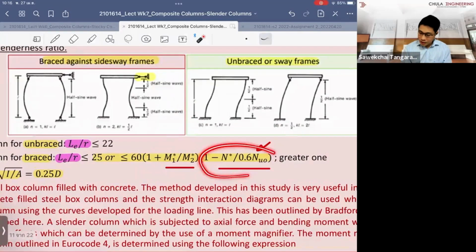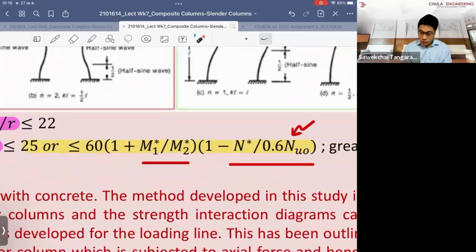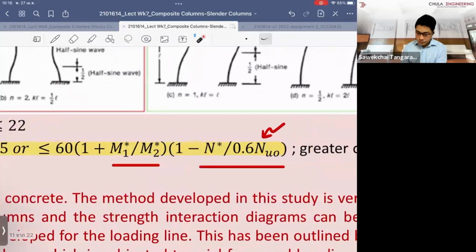The last term is the ratio between the F' and you have the star as well. Don't forget you need to come with the load factor as well, right? And we use it in all the designs. So you have to look at the load code in each of the countries that you're looking at. The load specification tells in the table that if you want to design for the axials or in this type of scenario, what is the combination that you have to look at in terms of the load capacity factors, and you find the worst case scenario.